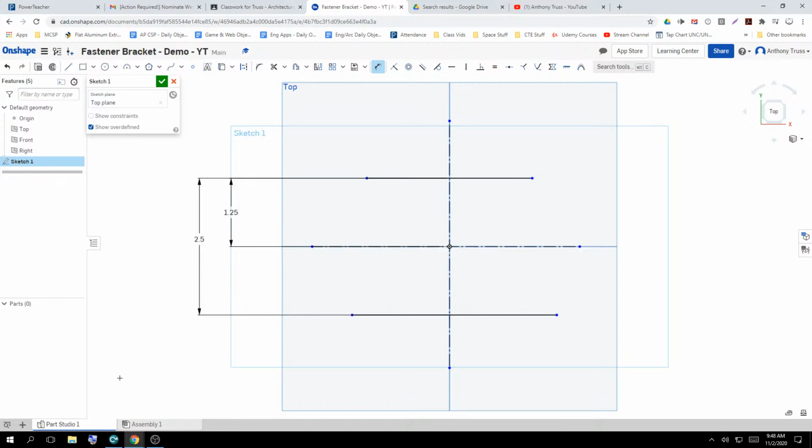That's going to make up the flats on the switch. I'm sorry, I keep calling it switch bracket, but the fastener bracket. And at that point, I know I have circles, right? If you look down at the top view of this, there are circles, and we know where they are placed in reference to the center of the part. And we know how big those circles are because it says drill 5/8, 2 holes. So that's what I'm going to do.